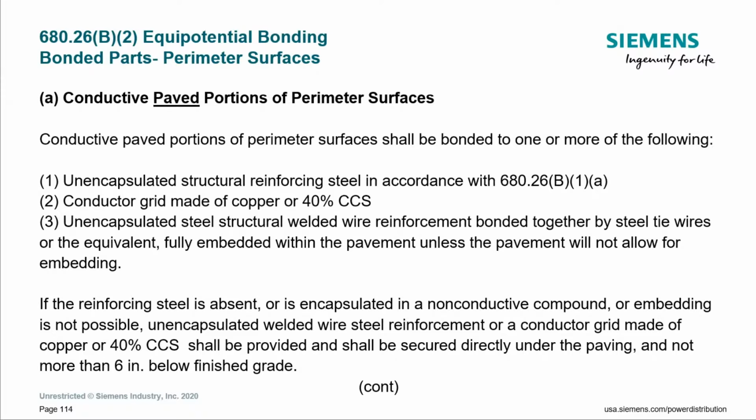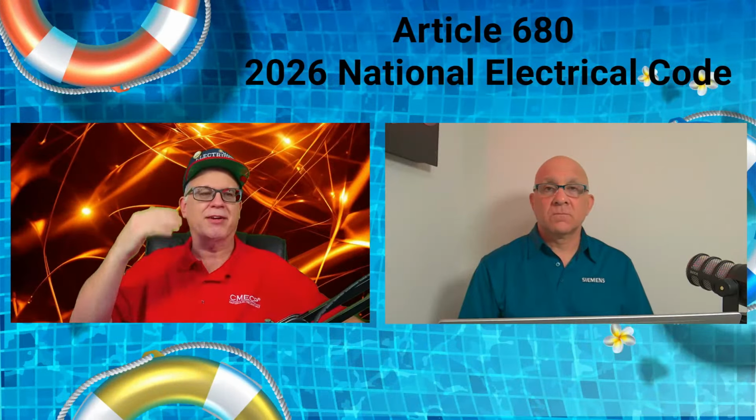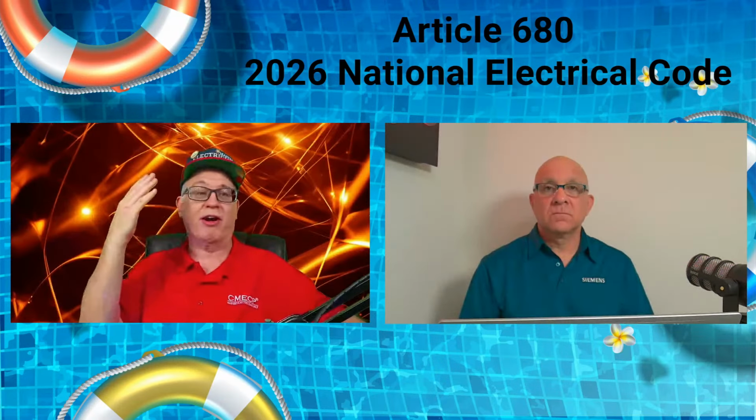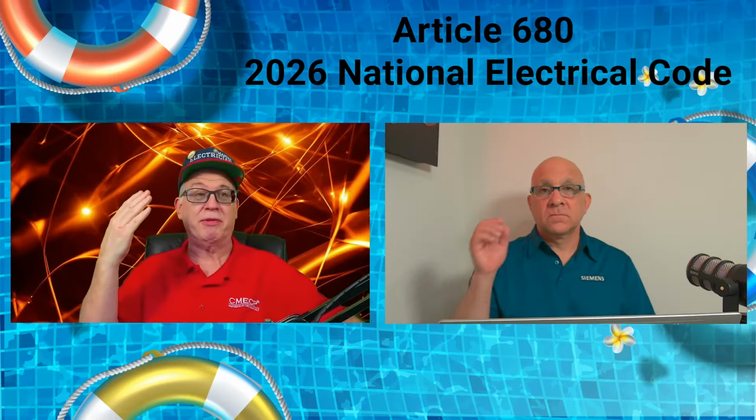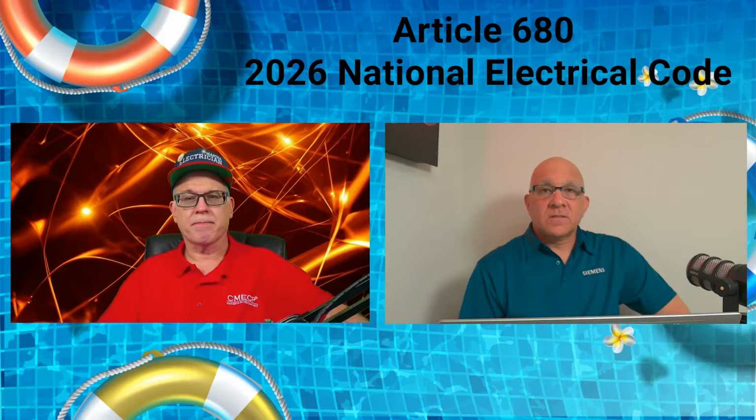I mean, I love selling copper. Don't get me wrong, I'll sell copper every day of the week. But the cheapest method is if they already have the rebar there. It's like a concrete encased electrode. If it's already there, for the electrician, that's the cheapest. It's already there, it's part of the structure. So what's missing from the list? In a nice way, you're saying there's something missing.